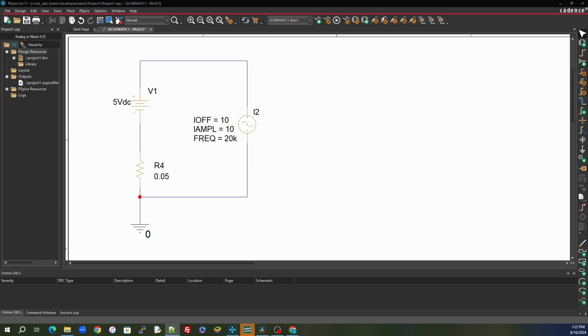So now let's get to solving this problem. What we want to do is go back to our basic one. We have our battery with its internal resistance, we have our current load, but we can't use the diode because the voltage drop on it drops our output below the 4.5 volt level. So we need something else to connect to the 5 volt rail right here.